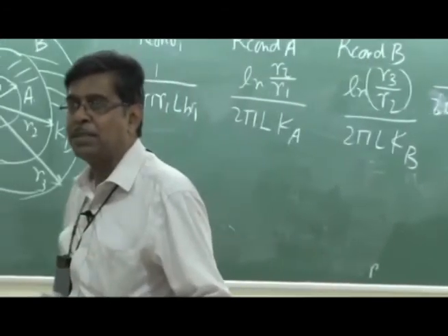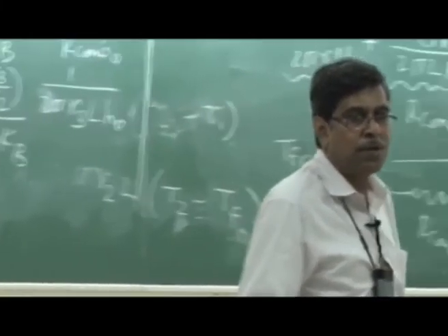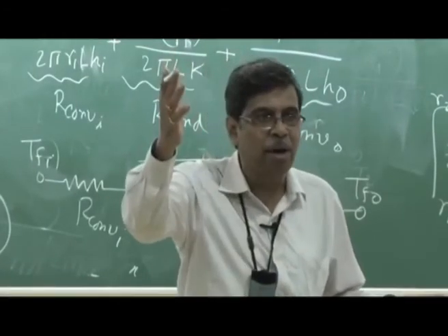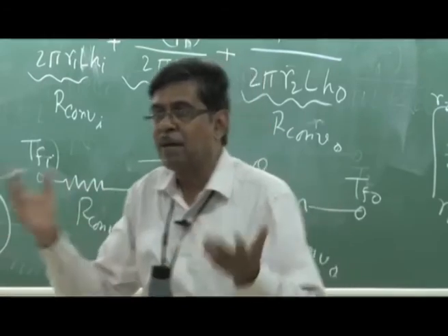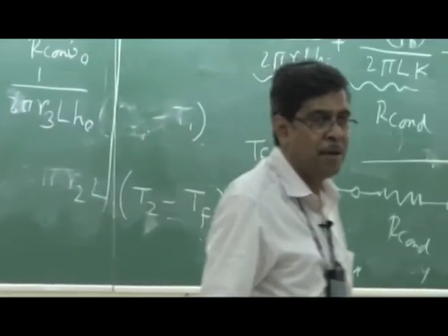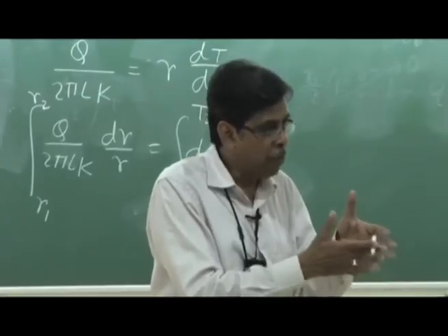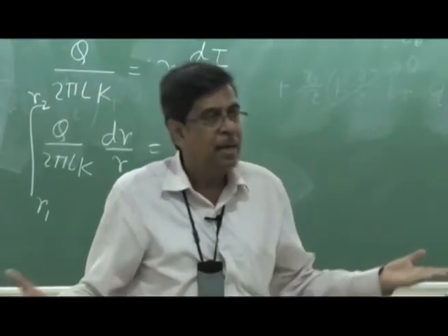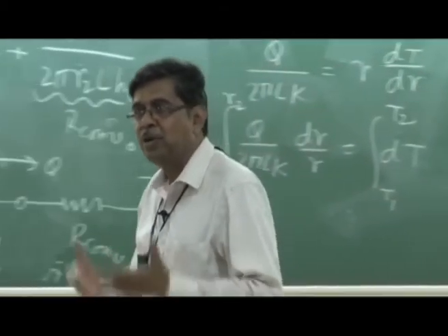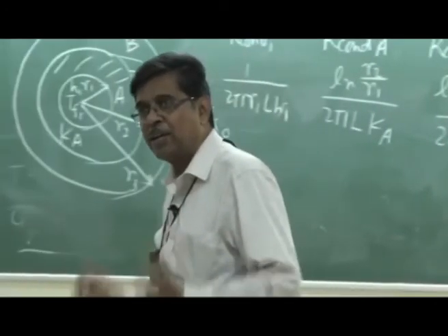This is a very general mistake in student days. I tell you, a teacher always tells his experience from student days. Students always jump to the general energy equation. He makes steady state, del T by del t zero, he makes Q zero, he makes everything zero, then you get d square T by dx square equals zero, so T has to be linear in x. Unfortunately, in one-dimensional heat conduction, this is an approximation of course, for a varying area, T is never linear. It is A into dT/dx which is constant. So dT/dx is inversely proportional to A. That concept has to be clear.